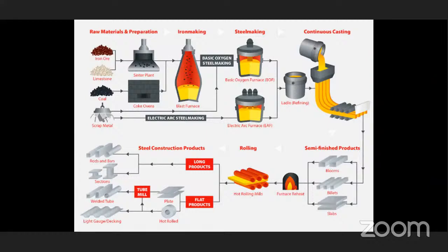So we have both acid steel making and basic steel making. We should remember that in acid steel making, the slag is required to retain the silica and manganese oxide. Hence the furnace lining in contact with the slag is made of acid refractory materials.